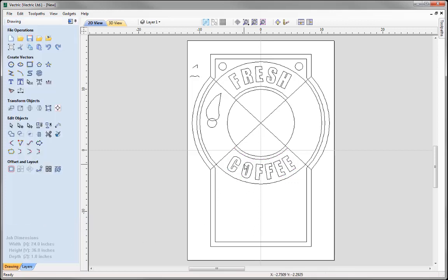Now not only do we have the option to alter the text spacing within that form that we was just in, we also have the option to do that outside. So I can select this text and I can use this option here, edit text spacing and curve. And what this will do, if I hover my mouse between any of these letters, you'll see that we've got two arrows that are pointing directly at each other.